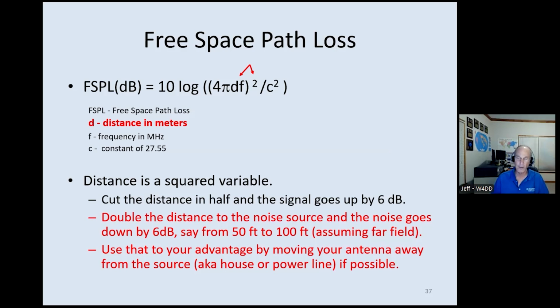But the thing to remember is to use distance to your advantage. Try to stay away from noise sources. Don't put your antenna directly over your roof, 3 feet off the top of it. Put it out in the backyard, in the woods if you can. Sometimes that's not possible, but it's best to let distance be your friend. Move that antenna away from noise sources. That will help you avoid hearing every small noise source.